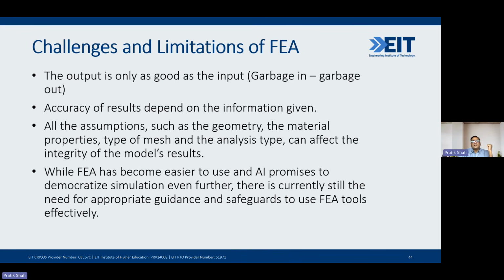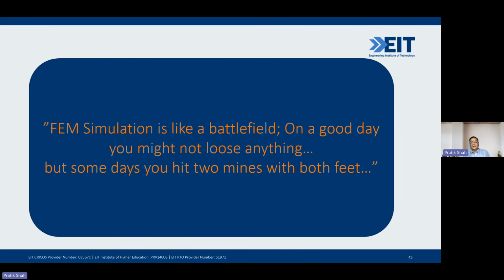I would rather say that it is garbage in and garbage out. The output is as good as the input. If an engineer is not properly understanding the physical conditions, then there are chances that he will end up with very poor results. The accuracy of the result depends upon the information given. There are many assumptions which are to be made during the process. If possible, we will also have some separate session entirely on FEA, where I would like to cover all of this. FEA at present is applied in all forms of engineering, whether it be structural, fluid, thermal, vibrational, any kind of tool.